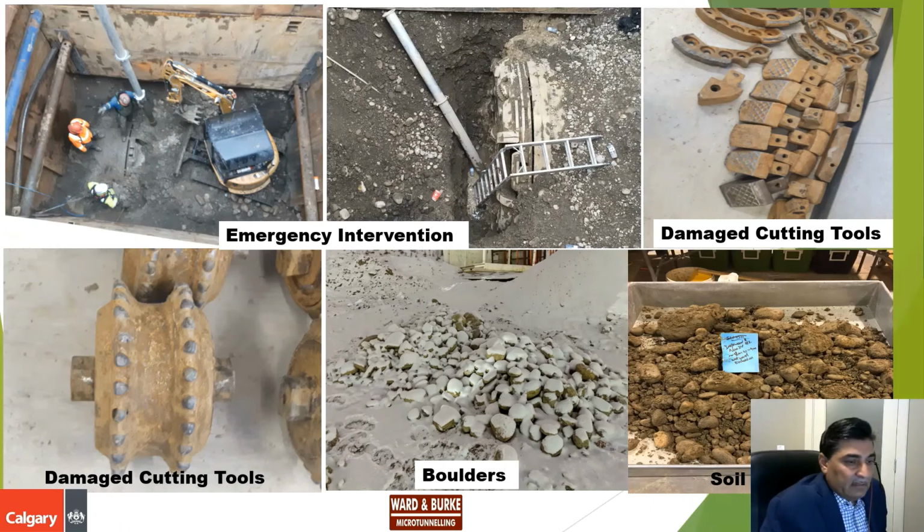So what is hard ground? At that location, the tunnel was in the coarse granular soil unit. That soil unit has boulders. So they submitted a claim, and for that claim, now we have to collect some information to see if that claim is valid or not. If, for example, our baselines are not correct, or the boulders that they encountered are more aggressive, then we have to pay them that claim. But if not, then we have to reject that claim.